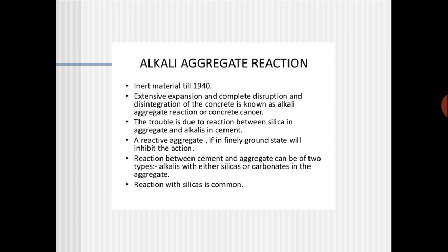So that is why the reaction between the alkali and carbonates is negligible, and that is why it is neglected. The reaction between the silica and the alkalis is predominant, and it's more commonly observed.